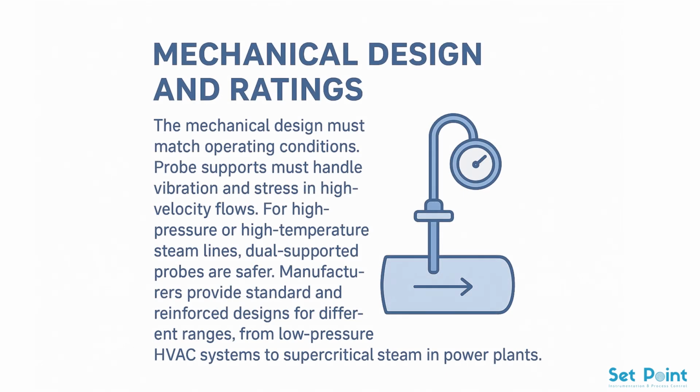Mechanical design and ratings. The mechanical design must match operating conditions. Probe supports must handle vibration and stress in high-velocity flows. For high-pressure or high-temperature steam lines, dual-supported probes are safer. Manufacturers provide standard and reinforced designs for different ranges, from low-pressure HVAC systems to supercritical steam in power plants.